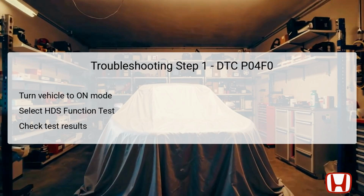The initial troubleshooting step involves turning the ignition switch to the on position without starting the engine. This allows the powertrain control module, PCM, to power up and initiate a systems check. Next, the technician should select the Honda Diagnostic System, HDS, and navigate to the function test to identify the status of the EVAP system.